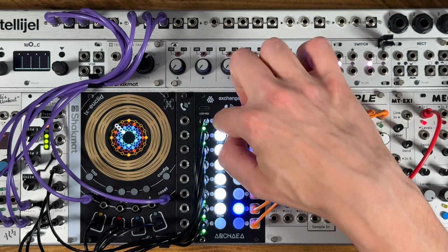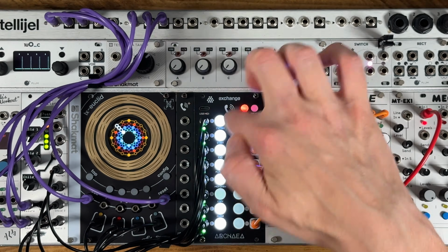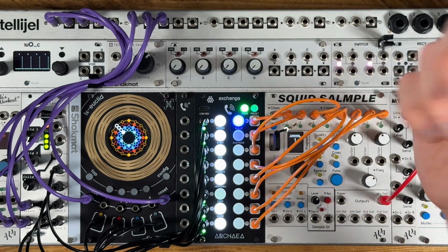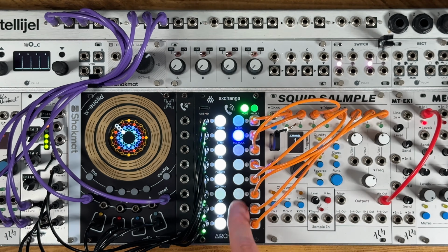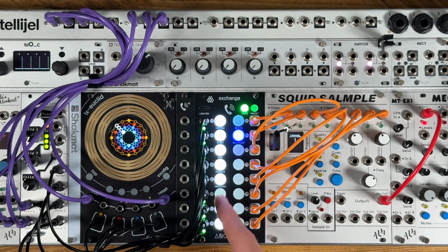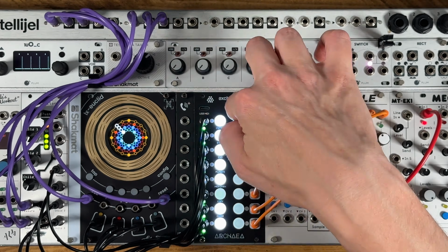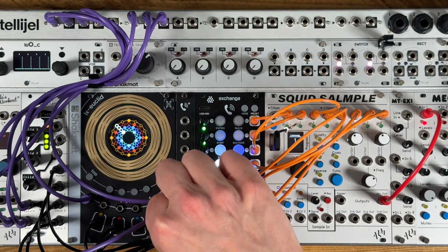If we hit mode and select the CV/trig page, this is where we get the options for our preset control input. These blue buttons on the right will select one of the modes. You need to refer to the manual for this. Basically, the top one is off, and the first one down is sequential triggering, trigger sequence, so they'll go through in order. Buttons 7 and 8 at the bottom determine whether it's the expander inputs that are used for this or the inputs on the module. With the blue lights unilluminated, it will be the ones on the expander. So let's come out of there and let's go into the input 8 on the expander.